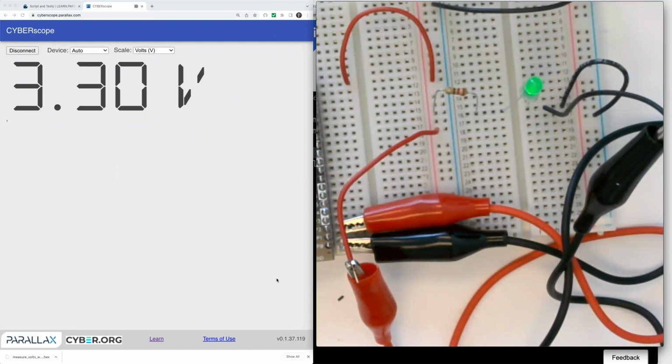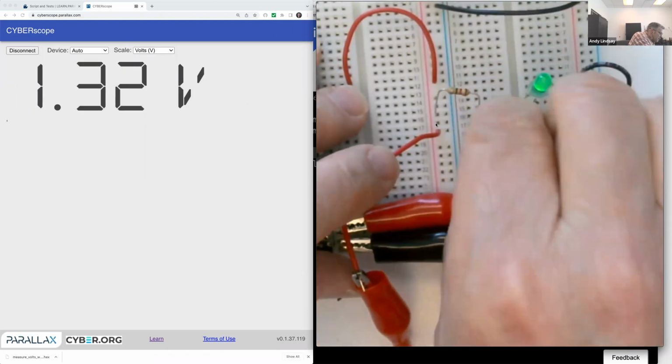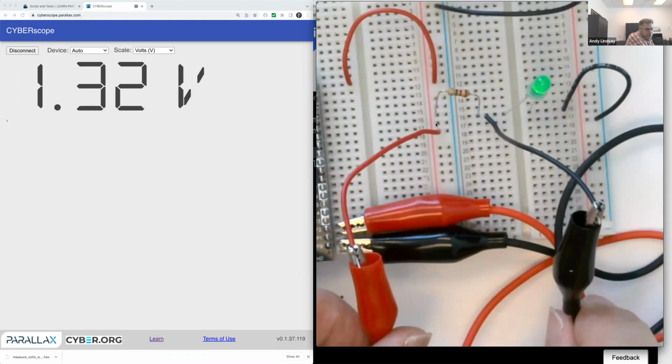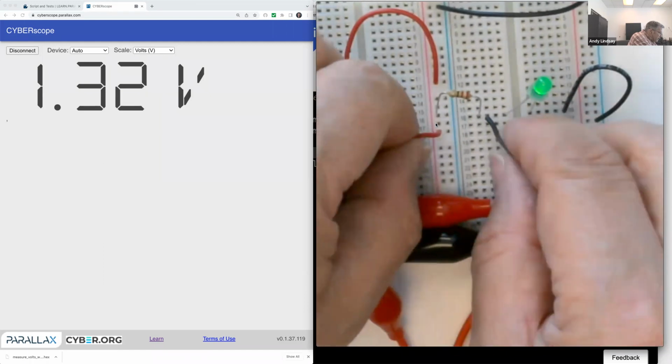Yes. This means that first of all, you've got your power connected properly, which is a whole activity that the students go through, and it's documented. And I skipped quite a few steps to get to here, because with 4.5 hours for a 40-hour course, we kind of have to do the survey thing. So here we are with basically proof of the voltage across each part. Now I'm going across the resistor, this part right here, and we see 1.33.